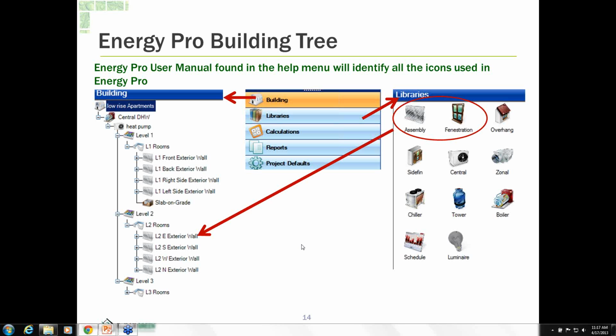There are many things that don't run in LRR, low-rise residential, but do in high-rise residential. So that's the thing. When you're doing a low-rise residential calculation and a high-rise residential calculation, you have to understand that you're using two different energy code compliance metrics. One for residential and one for non-residential. As far as the components go, all of the assemblies are going to stay the same. The systems are pretty widely different, and so are the calculations. So we're only going to be looking at the building envelope and what the calculations can do for the building envelope.